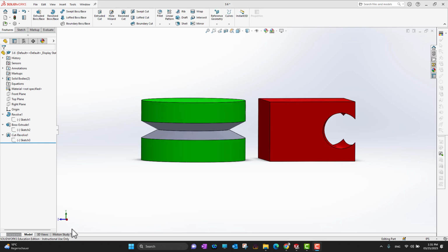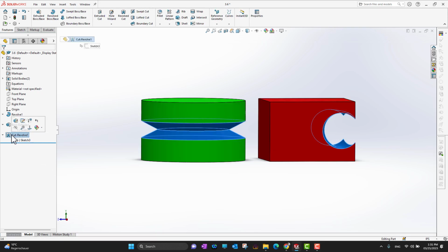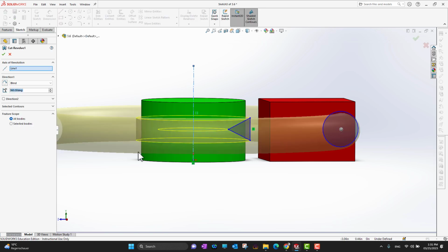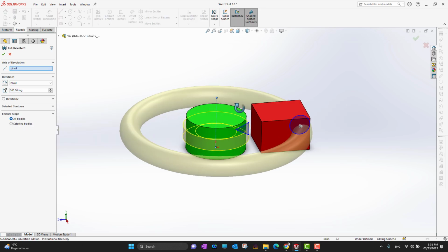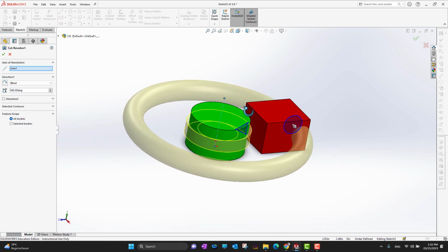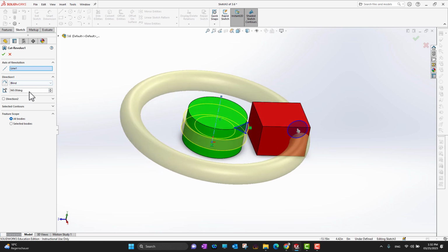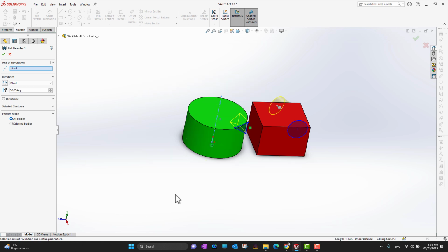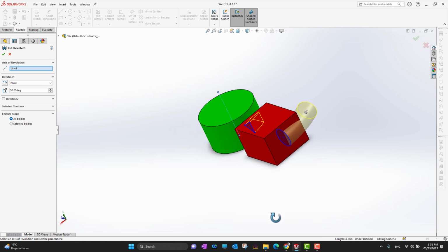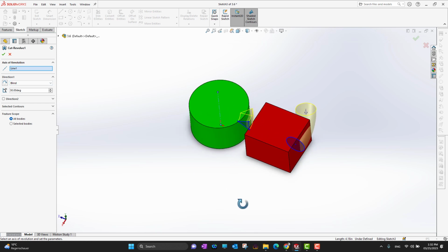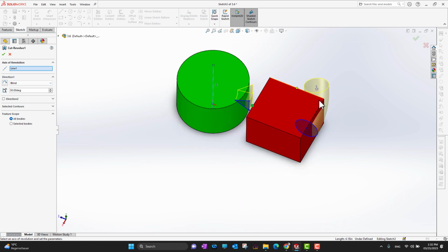And next what I want to do is, I just want to go back into the revolve cut feature and edit the feature. And right now, as you can see, we were using 360 degrees for both bodies and both sketches. So what if we want to have some specific degree revolve cut? Suppose I want to have a 30-degree revolve cut. So it can be in one direction. If you want to switch the direction, you can go there and switch the direction as well.